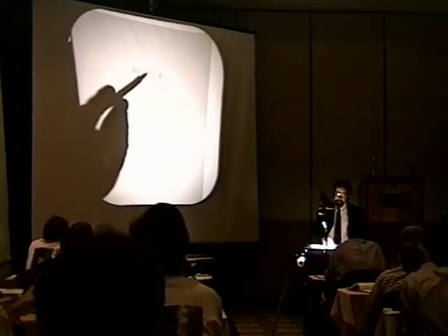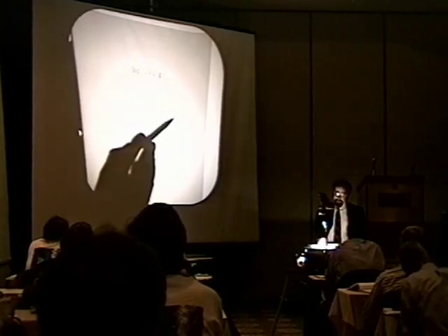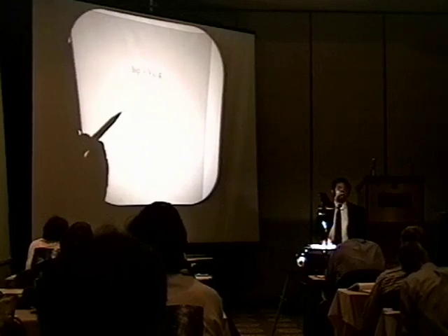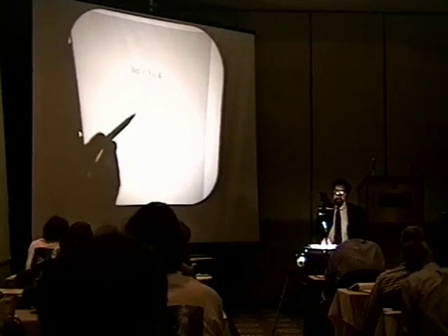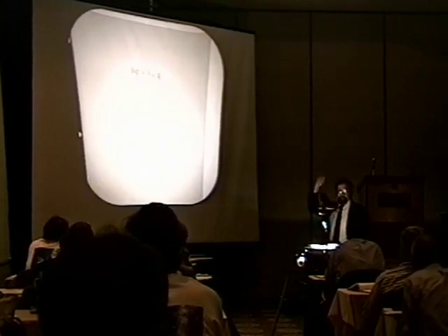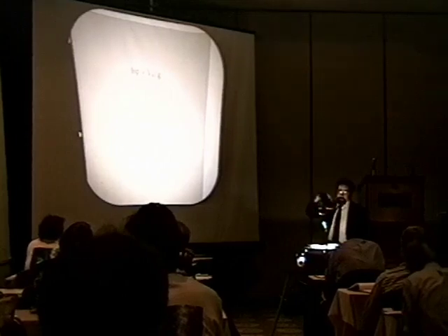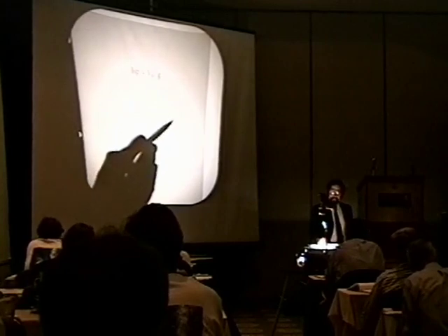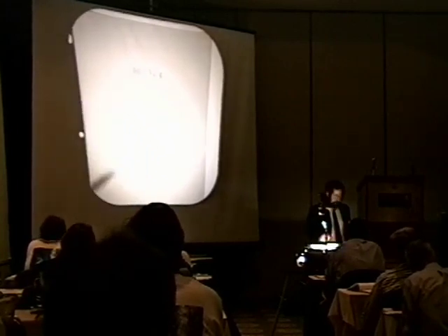Higher Isp means higher exhaust velocity, and higher exhaust velocity means that the initial mass at takeoff in your rocket, the ratio to your final burnout mass, can be smaller. It's not very good to have to carry a lot of propellant or have to launch from Earth with a very large, high mass ratio vehicle. So we want to get high exhaust velocity or high specific impulse.